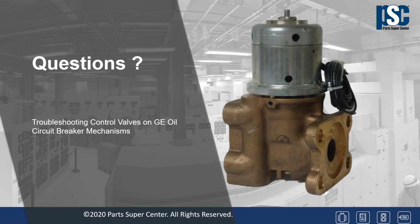That's a good question. They are metal to metal seats. So the pilot armature ball is stainless steel and the pilot armature seat is a bronze alloy. We coined those two parts together in the factory when we build these valves. So it's very difficult to reestablish that coining operation in the field. However, some folks have had success doing that.